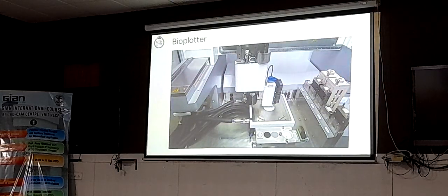We work at normal room temperature, or sometimes 20 degrees. So our parameter is nearby 20 to 25 degrees temperature, and printing speed is 2 to 5 mm per second. According to that speed, we print our scaffolds. But we are facing some challenges in getting the paste prepared. Initially the paste is not homogeneous, sometimes bubbles will be formed, and extrusion will sometimes create clogging and other issues. After multiple iterations, it gets smoother. Initially we face a lot of issues while preparing this.